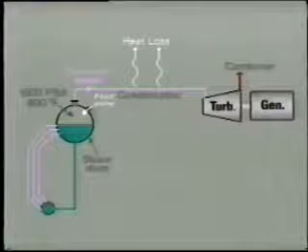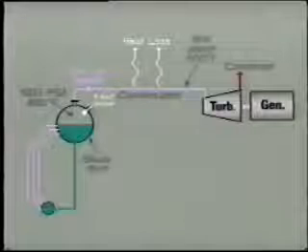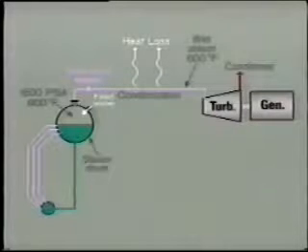This sounds like a reasonably high temperature, but we certainly cannot use saturated steam in the steam turbine. Why is this? Well, the problem is, as the steam is piped to the turbine, there is bound to be some heat loss, and this would cause a very small quantity of the steam to condense, so forming water droplets within the steam. This is where the term wet steam comes from.